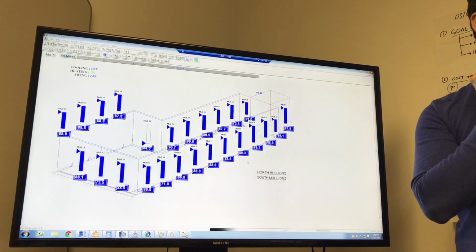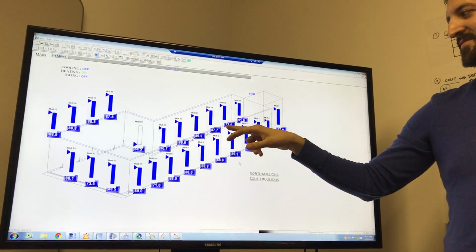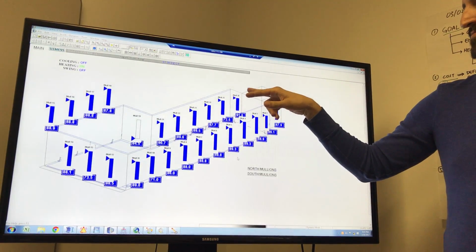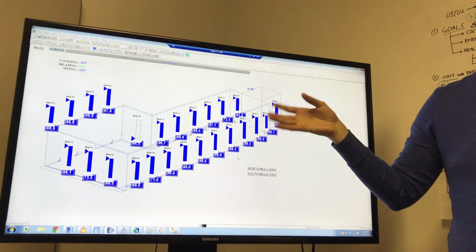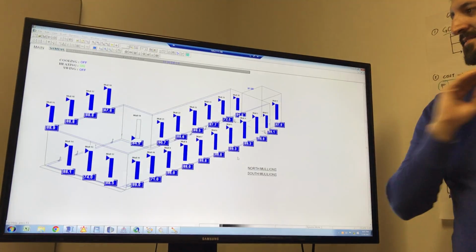And trying to fix it. Why is it not working, Chandler? Because the value is so low. So the value is basically room temperature. Room temperature, there is no difference. You want to have something which is close to your supply temperature, of course, minus room. Okay. But the stairwell one has been turned off completely by hand, the valve.